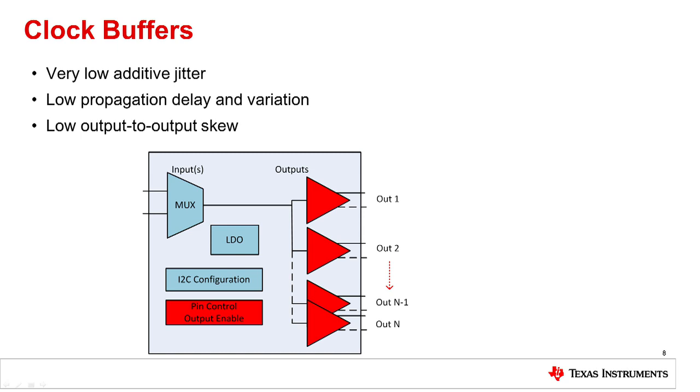You also need a way of configuring the functionality, such as I2C, SPI, or pin control, to select your desired input-output types and your I/O voltage levels to interface with the system needs. Typical formats supported would be LVCMOS, LVDS, LVPECL, HCSL, among others.